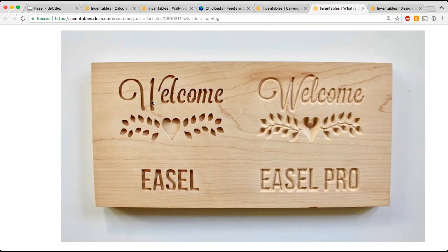You can see though, even some parts of the design, it couldn't carve, right? It couldn't carve this part of the W. If you've ever used the Lavanderia font in Easel, you know this problem well, right? It's almost impossible to get that font to carve out really nicely unless it's ginormous. But then look at this. Look at the same text with the V-bit.